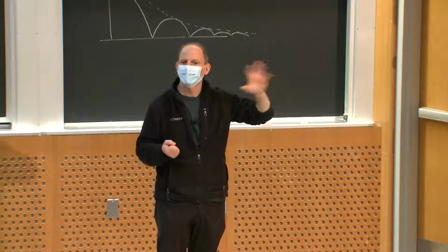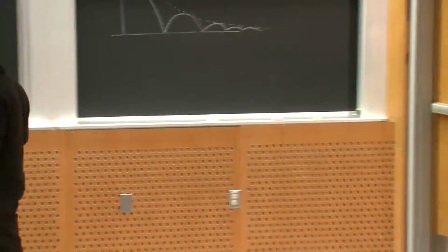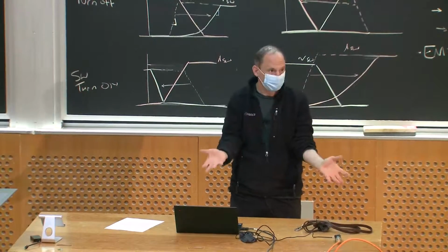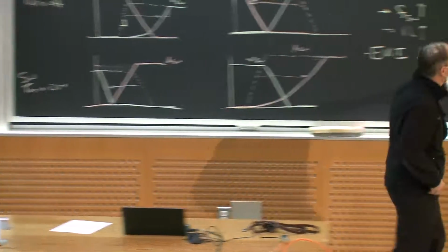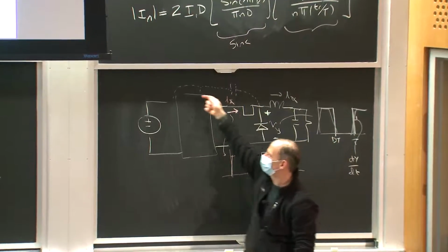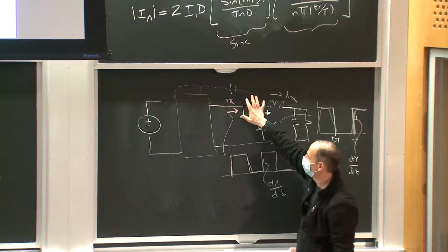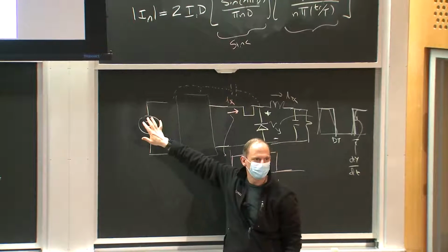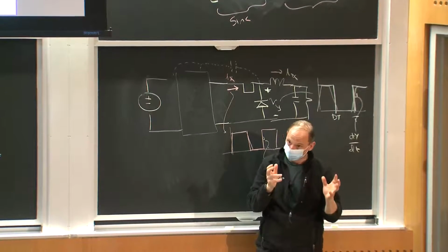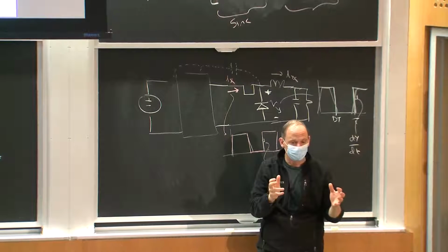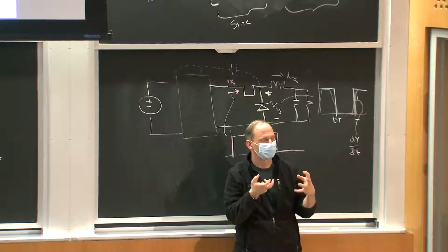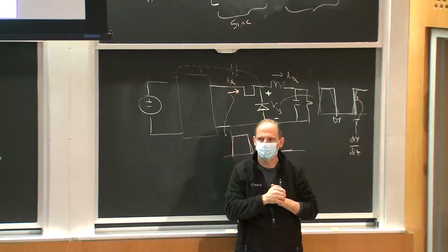So you might argue that the best way to get rid of the high frequency noise is, instead of generating and filtering it, just don't generate it. Or the stuff that's most likely to couple through, say, a parasitic capacitance is the highest frequencies. So if you just never generate them, it's a lot easier to filter them, okay? So you might not design your whole converter around this thought, but it really does help you with reduced filter size. And we've seen that with soft switch converters, you can often really make your filtering job easier.